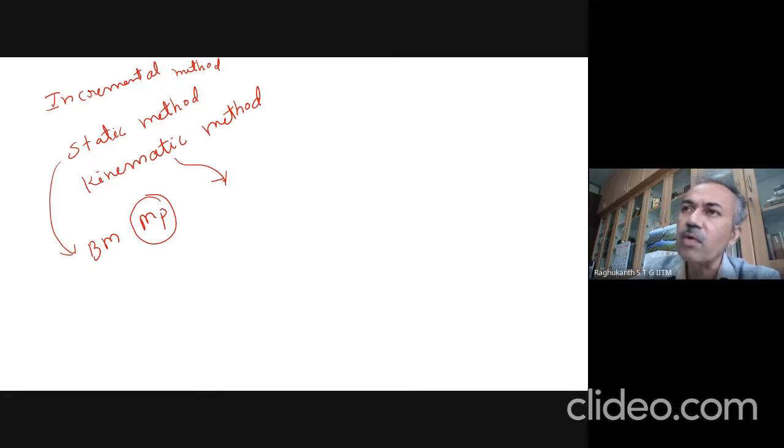So here also I told you we will be using that rigid link. This mechanism, you have to assume a mechanism. It is something like I already told you, eigenvalue, eigenvectors kind of a thing. You assume the mode shape, then you go back and find out what is the collapse load itself. So this is essentially the virtual work method. So these are the three main methods which are widely used.